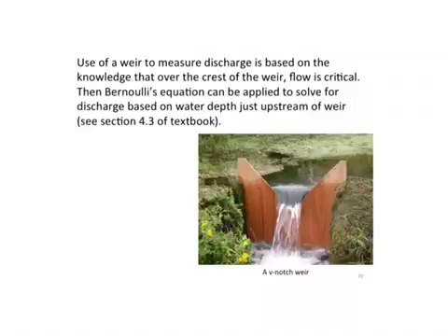Okay, in this next section, we'll be talking about how we actually might measure discharge in the field. So remember in class on Thursday, we talked about critical, subcritical, and supercritical flow. Well, it turns out that we could put structures in streams. We could put artificial bumps in streams that induce a transition from subcritical flow, seen upstream here, to supercritical flow, seen downstream.